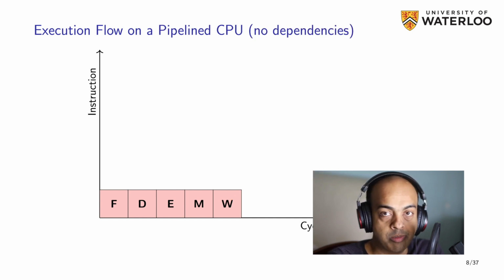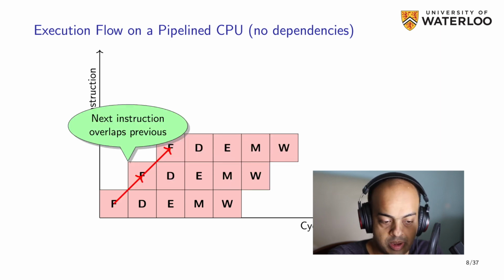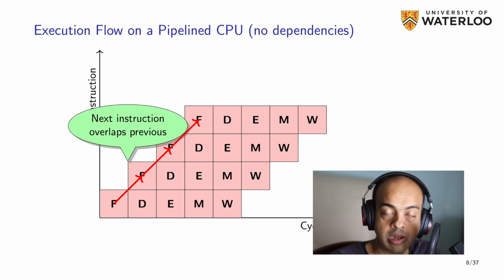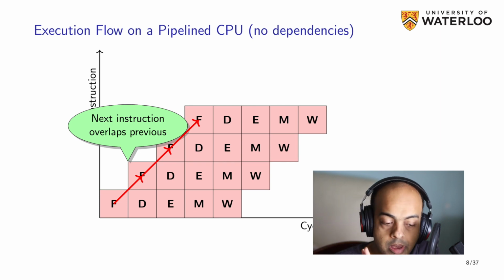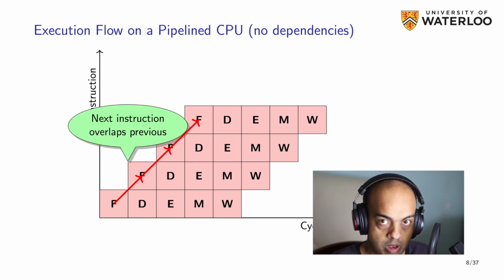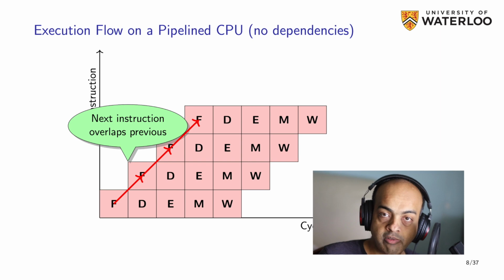Now, a more modern CPU that uses pipelining techniques is going to allow you to issue instructions back to back, right? Now, if this is a silly CPU, what you will notice is that it's going to issue instructions immediately back to back, and not worry about dependencies, right? So we'll revisit that later and see why we need to worry about dependencies. But the most important thing to take away here is that you are able to perform this sort of overlapped execution of different instructions in the hardware by using different parts of the CPU pipeline for different instructions,